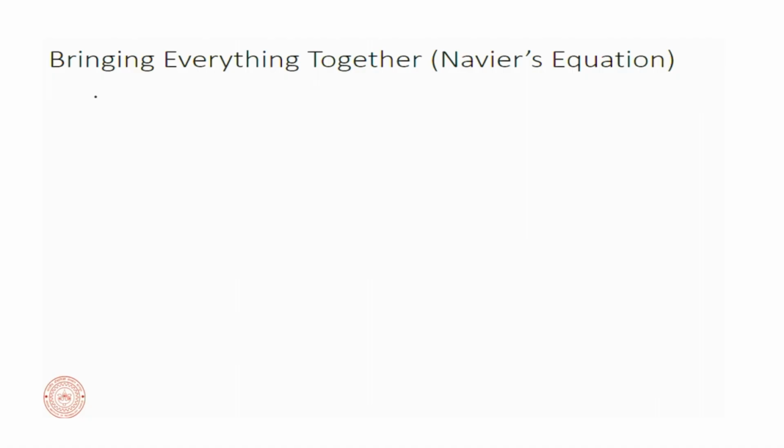So, now we have all the 4 steps ready. The last part is to combine everything together and to have one equation or one expression which will be entirely driven by the displacement of the body, and we will have some boundary conditions based upon the surface traction or the surface displacement. That was our objective, and this is the final modeling step for any solid mechanics problem. Okay, so we are bringing everything together.